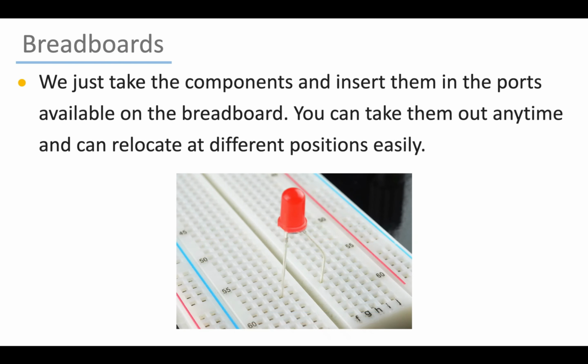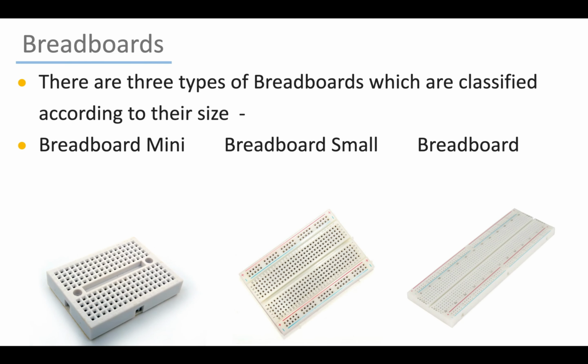We can just take the components and insert them in the ports available on the breadboard. You can take them out anytime and can relocate them at different positions easily. It makes circuiting really easy. Even if you are a complete beginner in electronics, you can easily work with them. There are three types of breadboards which are classified according to their size. It includes breadboard mini, breadboard small and breadboard, which you can see here in the pictures.